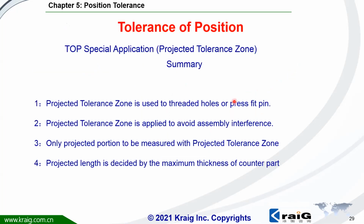All right. Here, projected tolerance is usually used for a threaded hole or press fit pin. That means the pin is pushed into the hole, not floating freely; it's a press fitting. Projected tolerance zone is applied to avoid assumptive interference. Only the projected portion is to be measured. That should be within the tolerance zone, right? Projected length is decided by the maximum thickness of the counterpart.